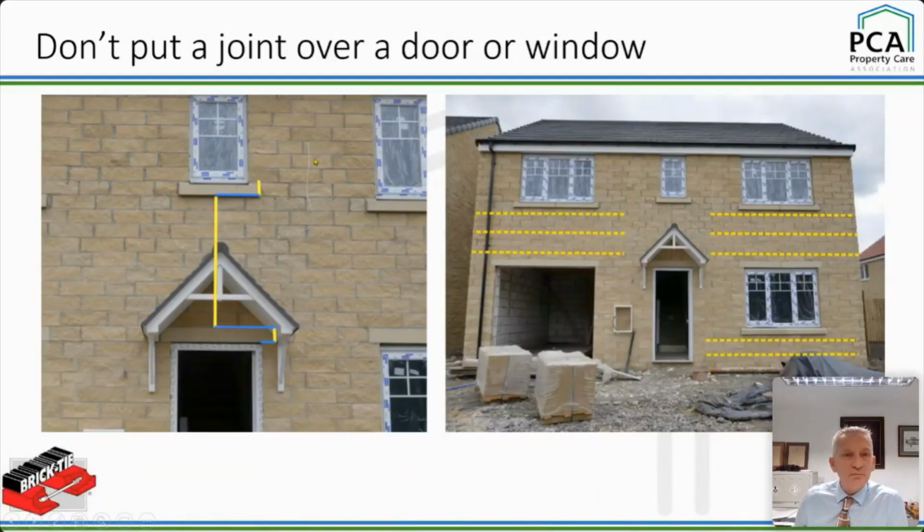Now, even though we put a slip plane around it, even if it was a perfect joint, we would also put bed joint reinforcement along there, because this is a slender panel. It's what's known as an at-risk panel, okay? Because it's low height. It's weak, even weaker than weak in tension, okay? So we put some bed joint in there.